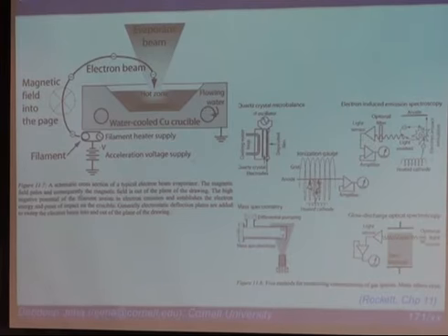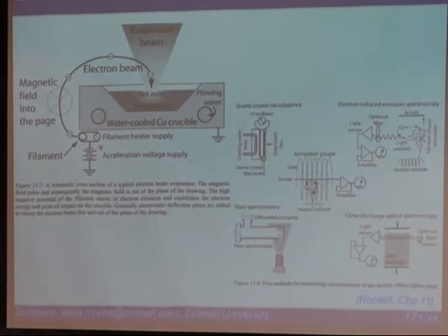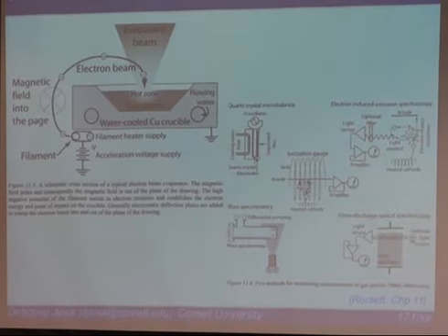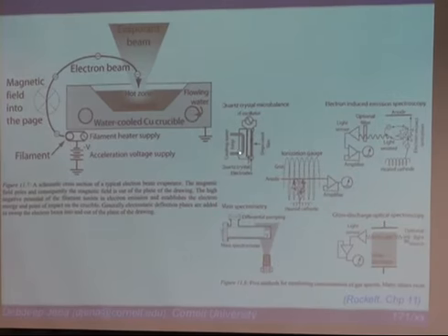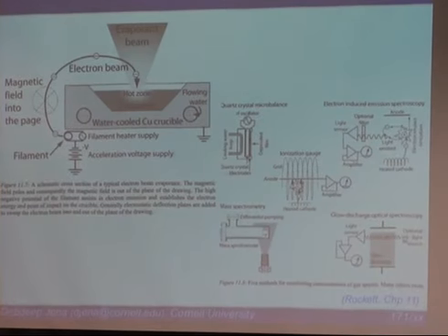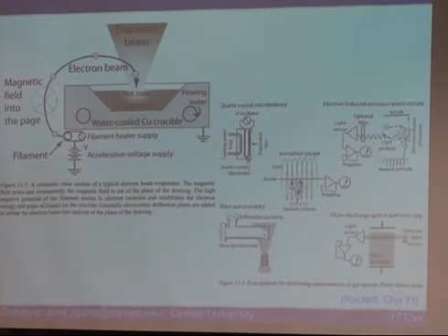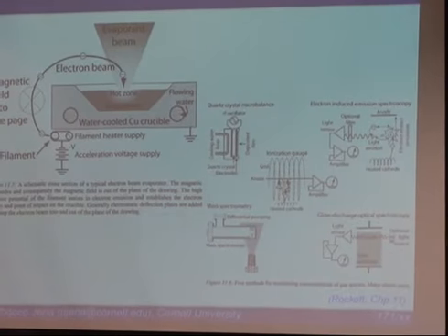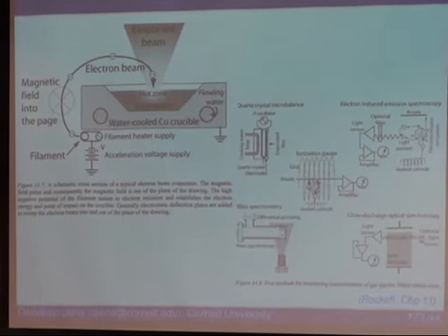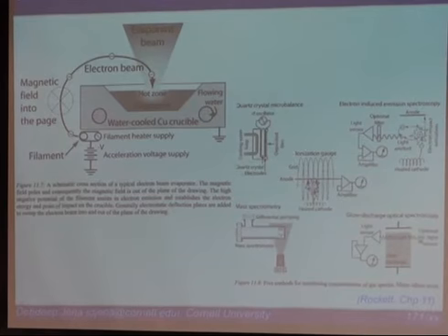How do you measure the fluxes? There are many ways, and I'm just giving you a laundry list here. If you want to measure just the thickness, what is typically used is a quartz crystal monitor, QCM. It's basically a crystal, and as you deposit stuff on it, you can measure even the minutest nanometers of thickness variations.